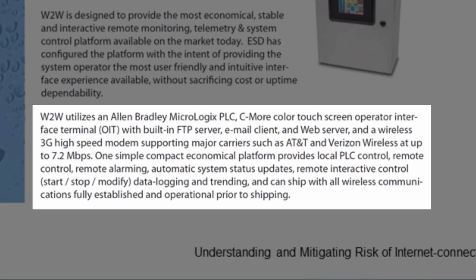In this case, it's one of those MicroLogix PLCs manufactured by Allen Bradley. They also throw in an AutomationDirect C-more color display panel. And what's unique about this panel is it has a lot of embedded capability. Some of that includes an FTP server. It also has the ability to email reports on a regular basis, and it has a built-in web server. All of those features seem very attractive when we initially reviewed this system from the supplier's point of view, because we needed to have those daily reports sent to us. We also needed to have the ability to have very simple remote graphics be viewable over this built-in web server.